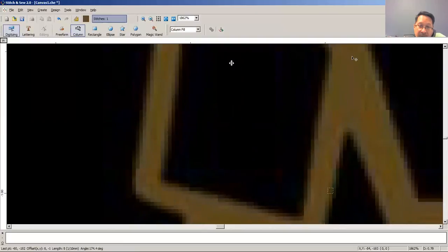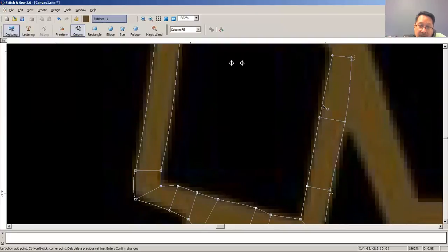And again, I'm going to run this into the body in a way that the angle is going to blend. By drawing the way these pairs are, this also instructs the program to make the stitches go at that angle by the time they pass through here. So in other words, this is maybe at this angle, but by the time it gets here, it's a slightly different angle. It's going to average the stitches out to a curve between the two like that.